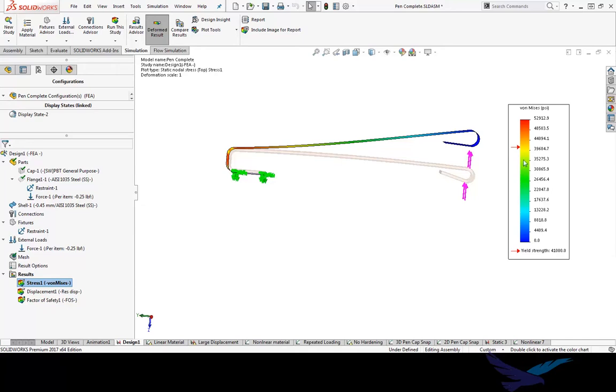So not only is it exceeding the yield point, but it's outputting a really, really high stress, right? In this case, if I were to run this problem and see that there's a pretty large stress here, we can't really say that the max stress it's outputting here is the true stress that the model is going to see, right? Essentially, we've exceeded